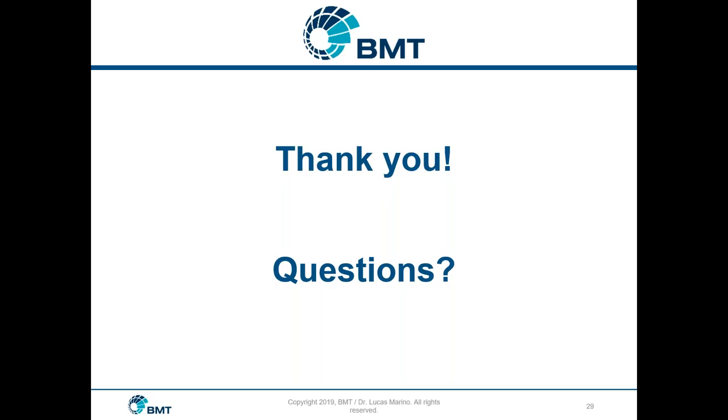Awesome. All right, so here's another one for you. Were you able to reduce your spare parts failures when you shifted from the OEM PMs to your own maintenance personnel PMs? In some cases, yes, and in some cases, no. Okay, because what we found was we were over maintaining our equipment to a certain degree in some areas of maintenance, based on the OEM recommendation.